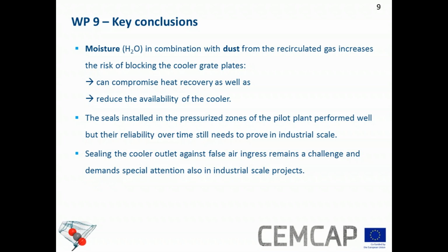So this is very relevant in a future oxyfuel project. The seals installed in the pressurized zones of the pilot cooler performed well, but their reliability over time still needs to be proven at industrial scale. They performed quite well because we didn't detect any CO2 leakages. But of course, the industrial operation conditions are more demanding, and the same type of seals should be tested.